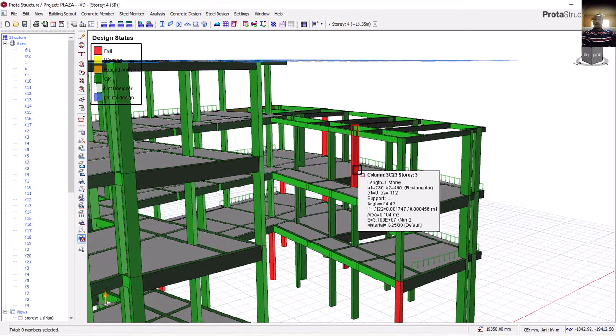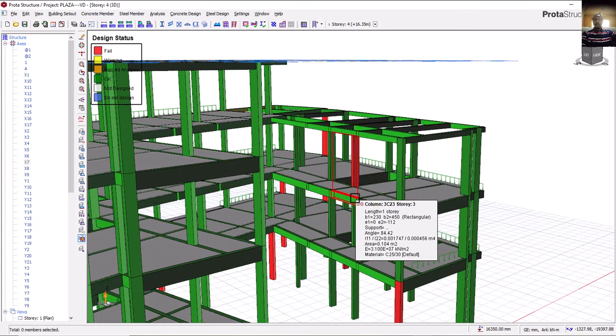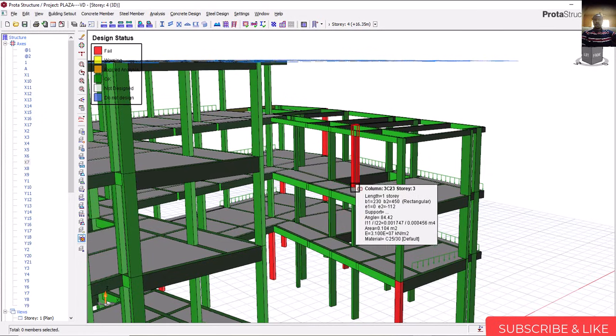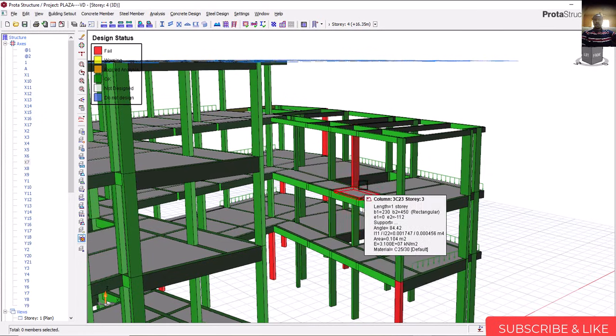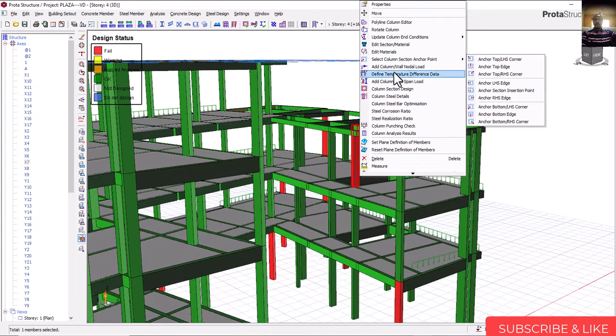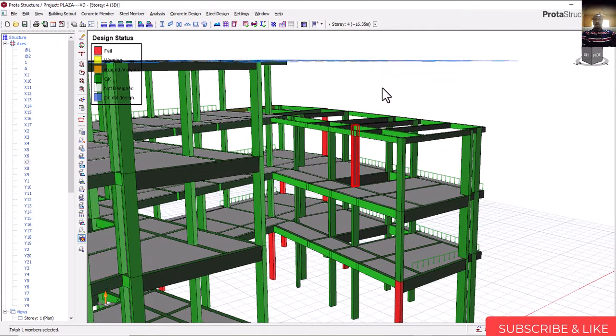So if I go ahead and use, for example, 500 and it's passed with 500, automatically everyone under it must be what? Must be 500. I can't leave this one 450 and now leave this one 500, because it's expected that even the lower column should be higher than the upper column. So the upper column should not be higher than the lower column. Is that okay? All right, so click on this now. Let's click on this, and then I'll come here.